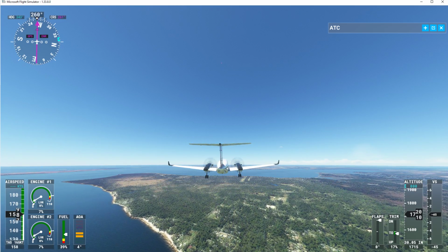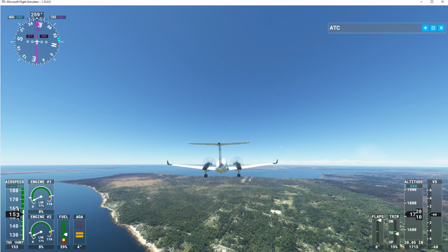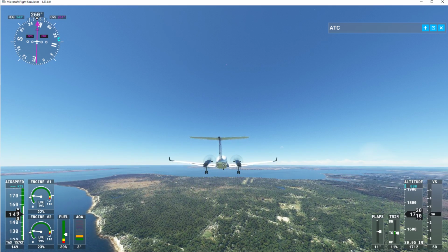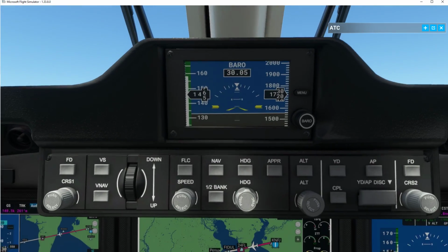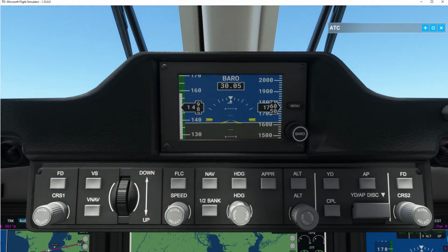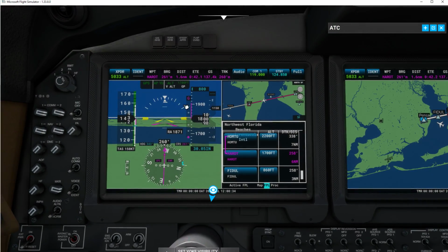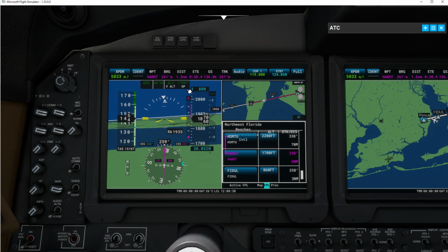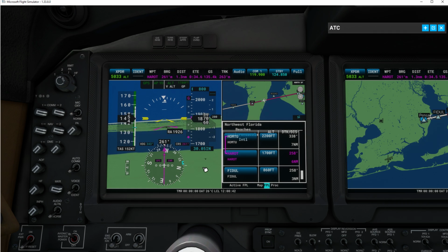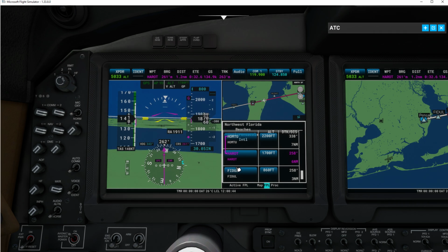And I'm going to get my flaps down, but I wanted to get my speed down a bit there. Nasair 616, you are 8 miles east of Pensacola. So you see this is on, Tower on 119.9 but it hasn't turned green, so we haven't picked it up. Pensacola Tower, Nasair 616, 7 miles east inbound RNAV runway 26 approach.